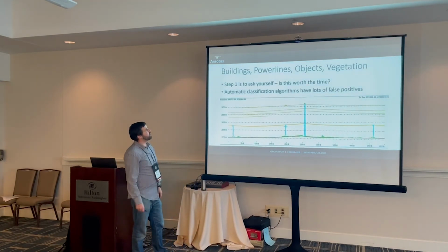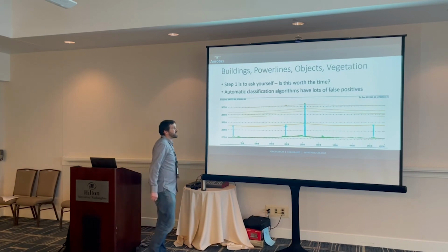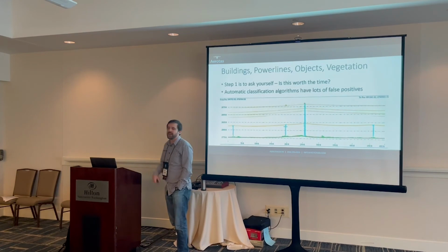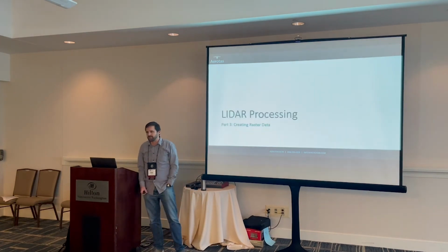And then buildings, power lines, all of that. Number one thing is ask yourself, is it worth the time? Automatic classification algorithms have a lot of false positives. We do start with automatic classification, but again, focus on ground, that's going to be the most important.